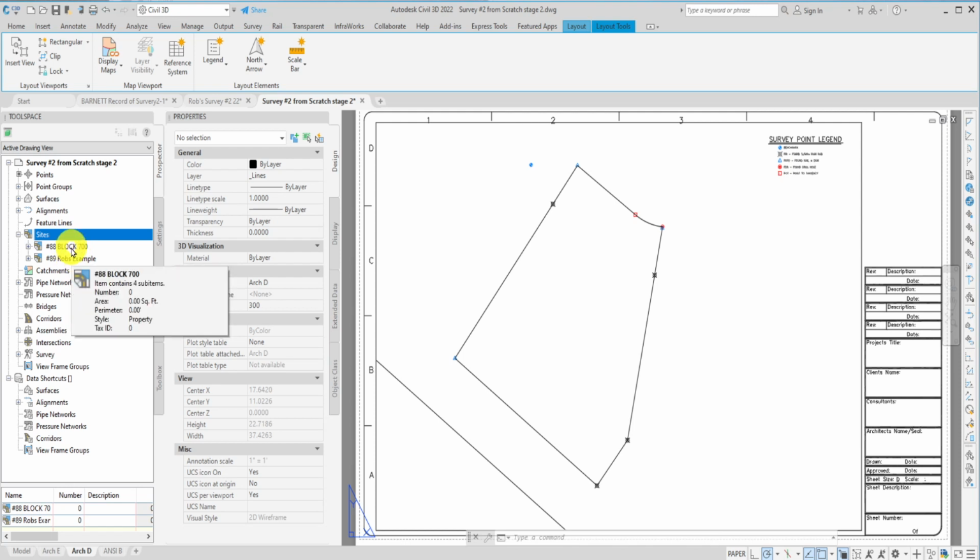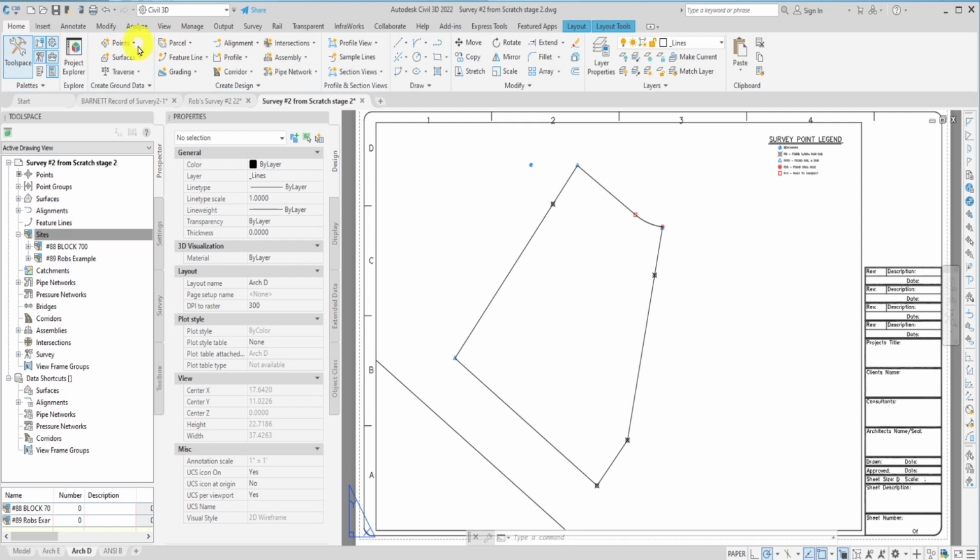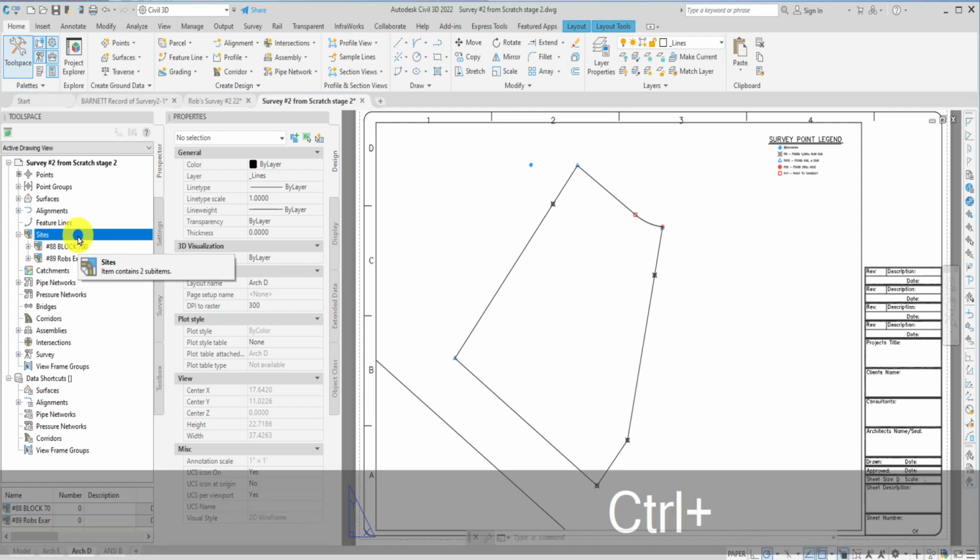All right, so anytime we're doing a project, after we create some basic AutoCAD geometry, one of the first setup tasks to do before we create any of these Civil 3D objects is to create a site. It's basically file preparation. Okay, so I'm going to close this video here so that we're only covering what it takes to make a new site. Hope this is helpful, and we'll see you as we continue creating new Civil 3D objects.